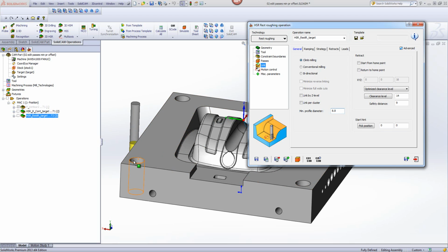The whole area that it has to clear over there is a total of only 20 millimeters. Remember, we have an offset of 0.5 millimeter, so we only have 20 millimeters. So this area is actually larger than this area over here. The 8.8 together with the tool comes out larger than the area of the hole itself. Therefore, it won't go in there.